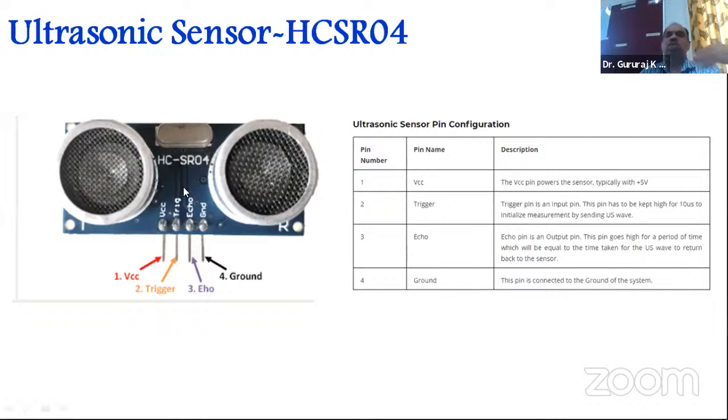So how these signals work: the ultrasonic signals are transmitted, and the other one will receive the signal. Now, we might have seen this particular set of sensors in our cars. On all the cars, we find these ultrasonic sensors. How is it that when these signals are transmitted and received, it measures the distance? And once an object is within a certain distance, it will give you a warning signal saying that some object is within the distance where you can collide with it.